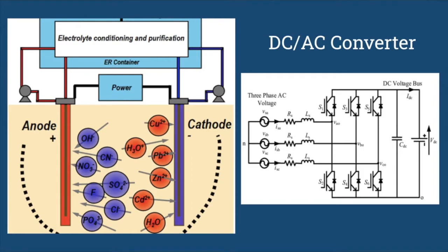Typical DC-AC converters are 480 volts and 3-phase, which can power an average of 3 anode sheets and 3 cathode sheets. These converters produce a low voltage, low amperage electrical field that polarizes the soil or sediment, causing soil particles to charge and discharge electricity. This causes the redox reactions that occur at all interfaces within the soil, the groundwater, and contaminant and electrode system, mineralizing organics and increasing the mobilization of metals. Metals migrate to the electrodes where they are deposited and removed with the electrodes. The converter is controlled by an on-site computer system.